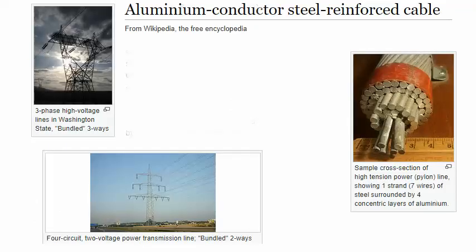Let's start with one of the biggest wires, aluminum conductor steel reinforced cable. These wires have the biggest diameter and thus the lowest resistance. The goal of manufacturing and connecting these huge wires is, of course, to have the minimum resistance possible, but you probably won't find their properties described in ohms or ohms per mile. Rather, you'll find it described in percent of lost power per mile or per 100 miles.